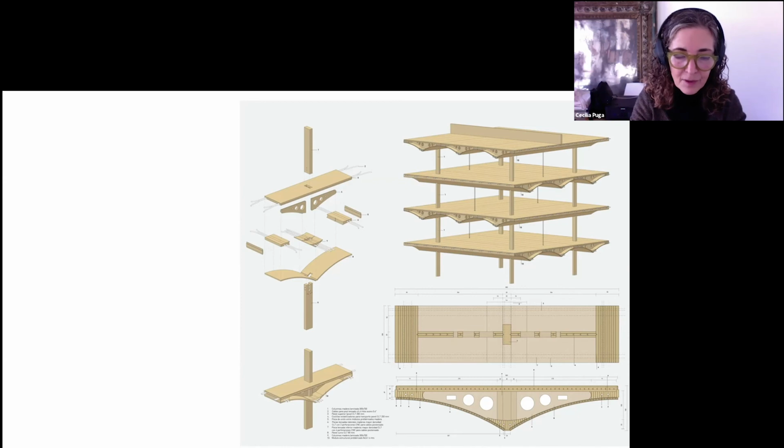In order to avoid a strong transfer of tensile load at the joint, the slab element will be assembled using post-tensioning cable linked to the wooden element located at the top and bottom of the beam. The corresponding area will be extended using solid wood blocks. The well-known post-tensioning technology of reinforced concrete structures will be adapted using 4 0.6-inch wires placed in a steel duct filled with injection mortar after post-tensioning. Anchor heads will be placed at the end of each beam. The static calculations show the post-tension cable can easily take up the tensile forces.